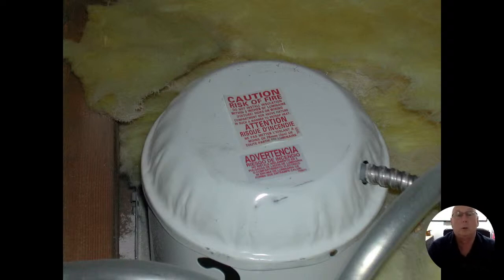All right. So there's two different types of can lights. The one we're looking at here is what they call non-IC rated can lights. IC stands for insulation contact. That means if it's non-IC, insulation cannot touch this can light. Typically, they're painted white. Not always, but typically they're painted white. If we're lucky and we see them, you could see the old sticker right on there that says you have to have 2 inches or 3 inches of space around this can light. Now they do make boots that keep the insulation away from the can lights, and I've seen people put boxes around it to keep the insulation from getting around it. But these are pretty drafty as well.